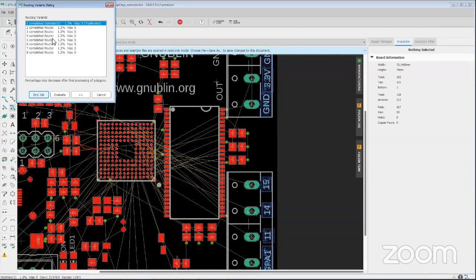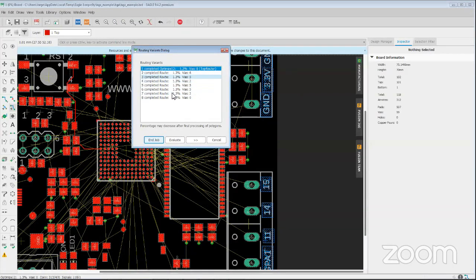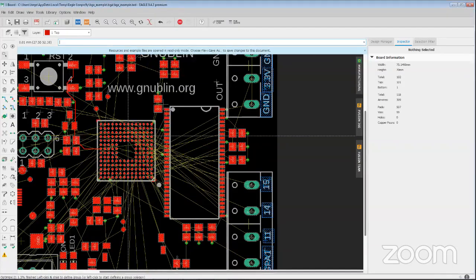Okay, but you can put in a list, all separated by spaces, to route specific nets. You can also tell it to route everything but, and the way you do that is auto, exclamation mark, and then the different nets separated by spaces. So there's a lot of power in the command line utility of the Autorouter. So I'll say all in job with that. You can see it routed that reset line that I wanted.